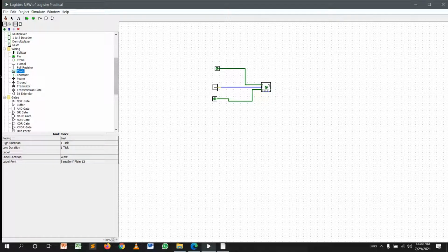The clock input and two outputs are here. You can see the first output and the second output. Then the toggle situation is when the two inputs are 1 and the clock pulse must also be 1. Now you can see the clock pulse changing from time to time, and both outputs also change. Now, this is the toggle situation.